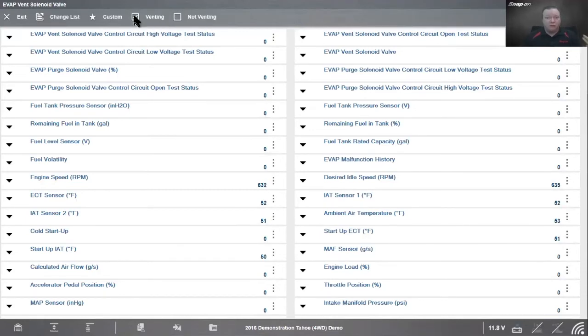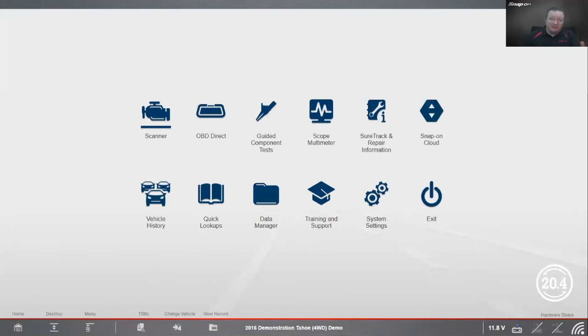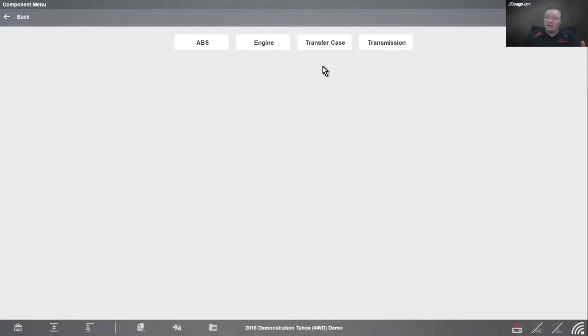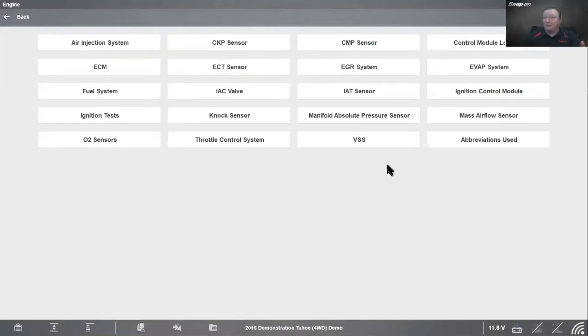Once again, since we're wirelessly connected, we can just go underneath the back of the vehicle, put our hand on it, go to venting, go to not venting, and make sure whether or not it's clicking. In this case, let's say, for the sake of argument, that it is clicking. But of course, we also want to verify the voltages are correct, because we can have problems with parts brand new out of the box. Pretty sure you may have gotten a brand new part in a box that didn't work at one point in your life, right?